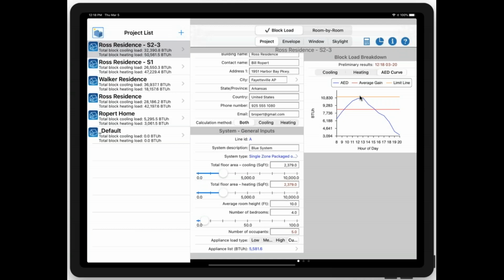Yeah, what would you use for a multi-zone, a package like a Mitsubishi system? What system in your pop-up? Because it doesn't seem to apply directly. Are you talking VRF? No, I'm talking about a heat pump system for heat and cool. Yeah. Would you have a heat pump per floor, or how would that work? I've been using ducted units within the space and a single outdoor unit feeding 3 or 4 or 5 air handlers.